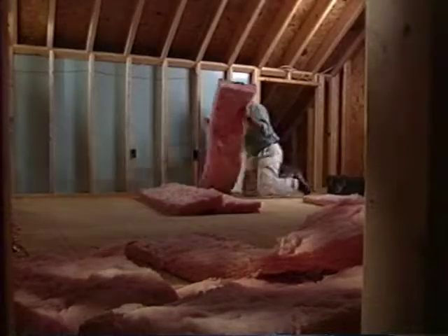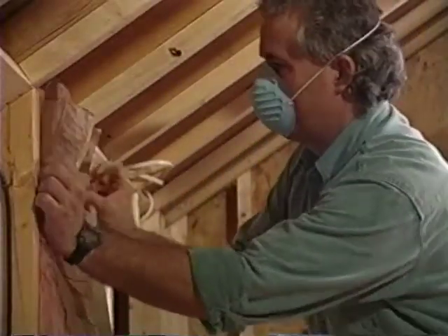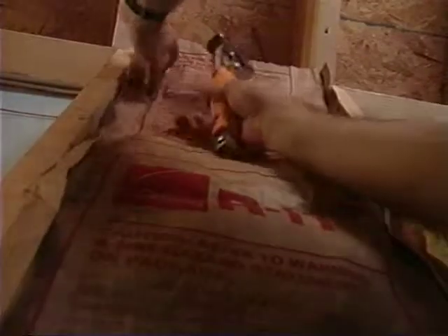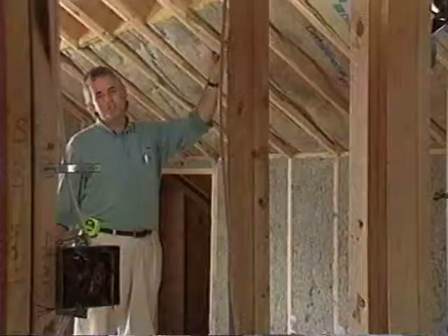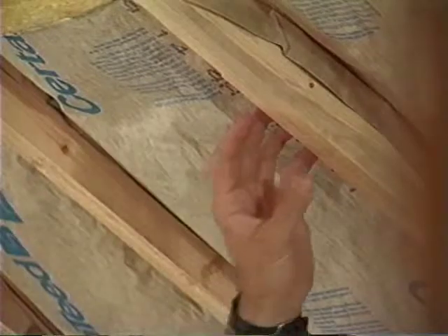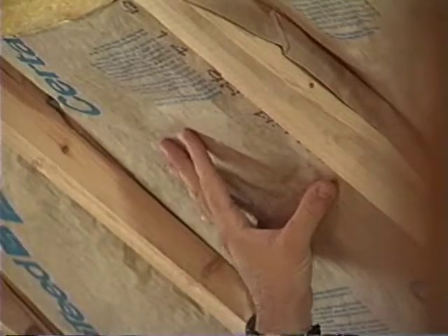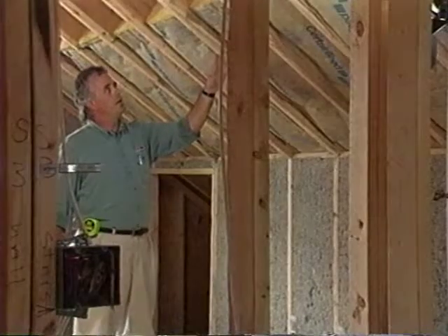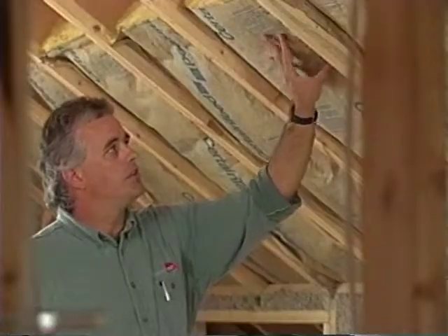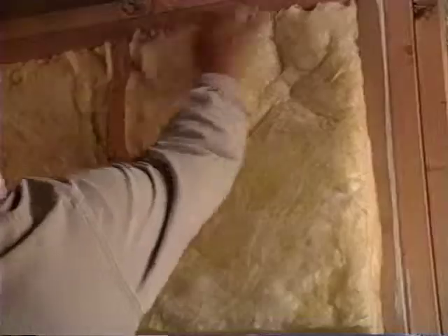Dan McFarland is a former insulation contractor and now works as a building science specialist. He says compression is one of the most common insulation mistakes. In this situation, the framing contractor has furred out this 2x8 an additional 1.5 inches. This will accommodate an R30 bat of fiberglass. But the problem that we have is when the insulation contractor came behind him and installed his bats, he pushed them in too far, compressing them. Compressing the insulation means that they're not getting the full R value that they expect, and that's what they plan for, to have comfort up in this bonus room.